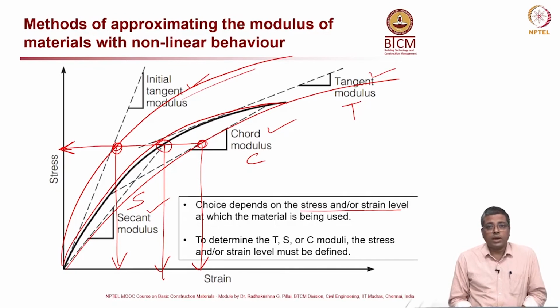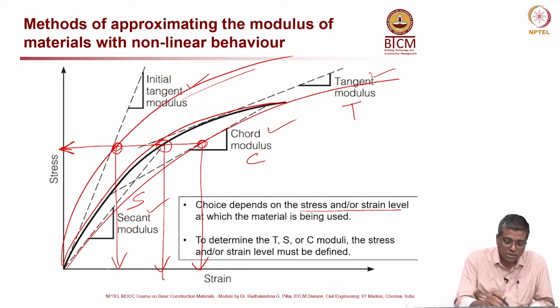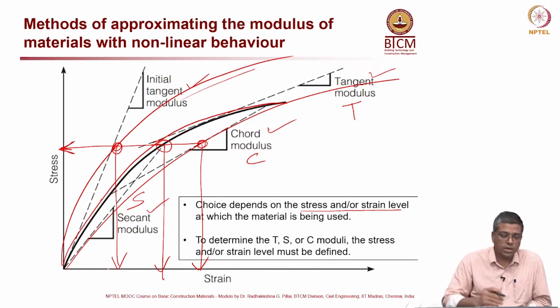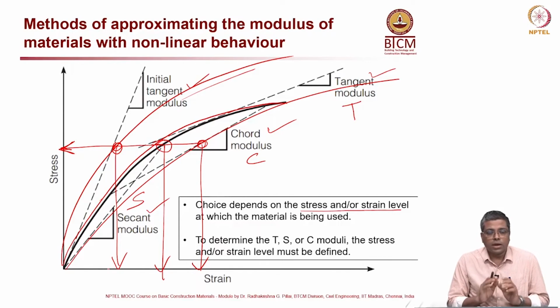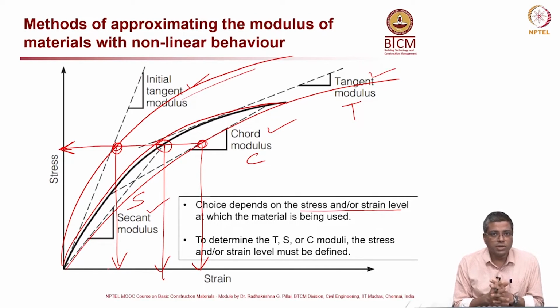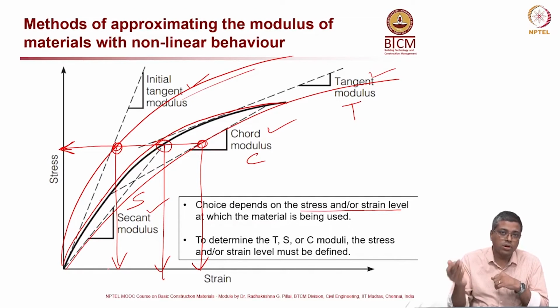So, based on that you can decide what would be the strain experienced by the material if my options are A, B and C, 3 options, for which I draw 3 vertical lines here. Like that you can get the stress-strain graph of various materials which are available for use, then decide the stress level which will be experienced by the material while in use, and then based on that you can decide which material to take, whether the strain is beyond the limit or not.